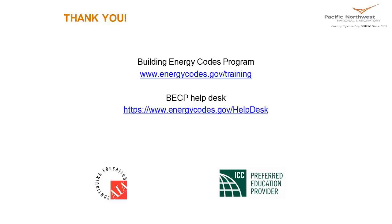U factor times area. And those are all prescriptive, except the last one, the total UA, allows you to do trade-offs in between your assembly components. If you were just to do the U factor alternative, you're going to the U factor table, and again, it's prescriptive, and each individual assembly would have to meet that minimum U factor in that table.